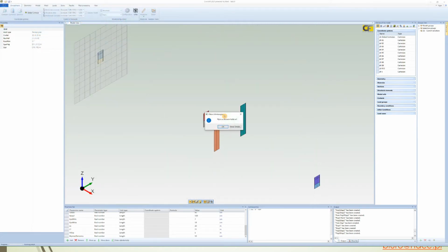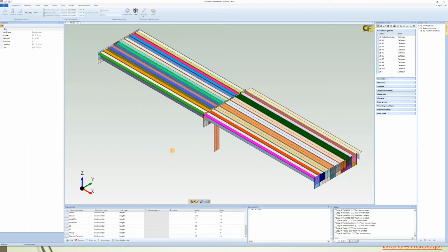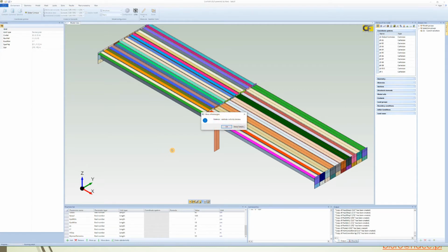This cross-section can be used to generate the beam in the longitudinal way, and then it is copied and transferred in the transverse direction, one single beam. Also, all this geometry is generated through different parameters. If we modify those parameters, the geometry is updated.